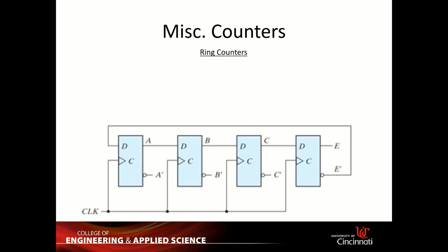And this is the last counter that we're going to go through. This one is called a ring counter. It's similar to a normal shift register, but the last output will tie back to the first flip-flop input. I don't know if you remember, or you can go back to the registers lecture, when I tried to transfer the value of register A to the value of register B, but I also tried to keep the value of register A in existence. In that exercise, I also did the same thing. I led the output of the last flip-flop back to the input of the first flip-flop.